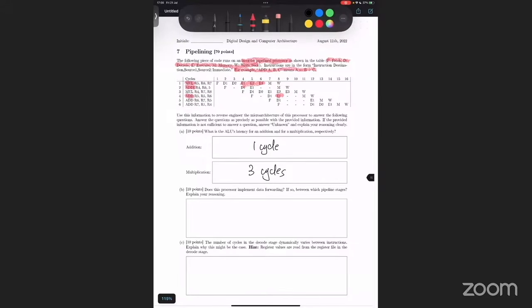So we should look at the later half of the pipeline to see whether some data-dependent instructions have already resumed execution before the input data is written back. So the first step is to find the instructions that have data dependencies.